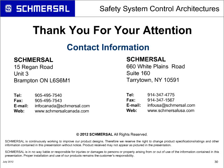I'm just not sure about that, but no matter what you do, whether it's a variable frequency drive or a servo drive that has the safety on board, like a safe stop or safe torque off type of feature, always refer to the manufacturer and their installation instructions, because they typically have had that drive approved by some sort of third party like BG or TUV to meet a certain control category and performance level.